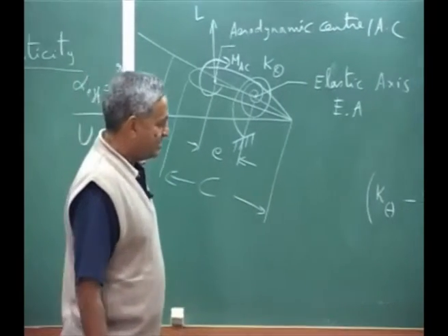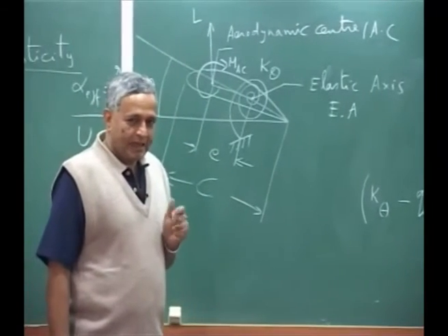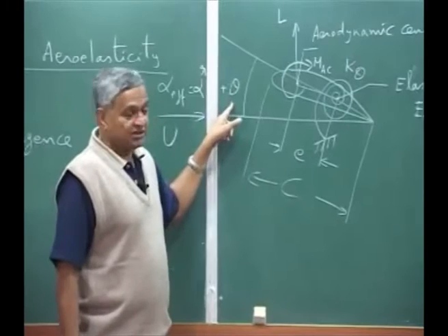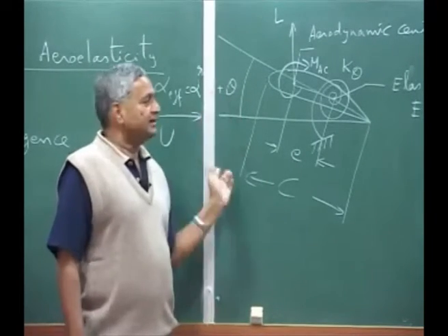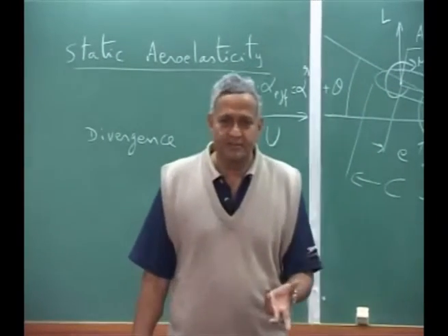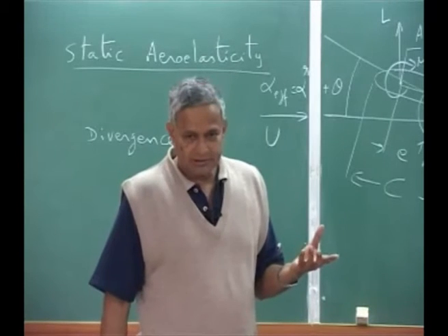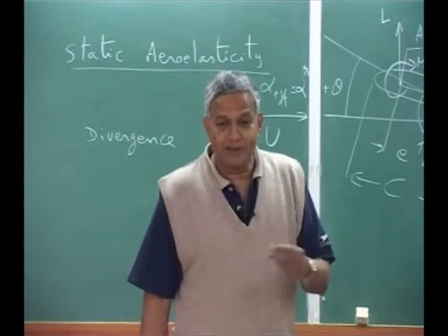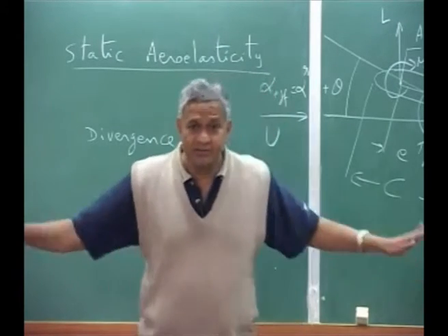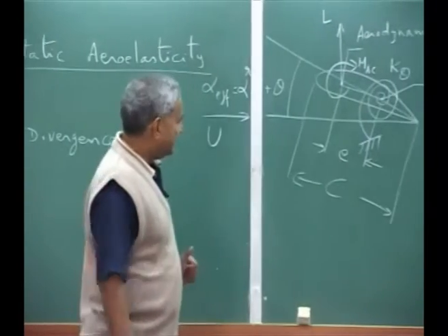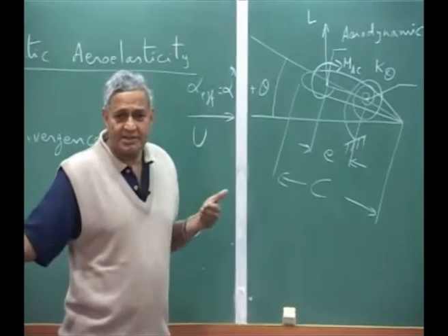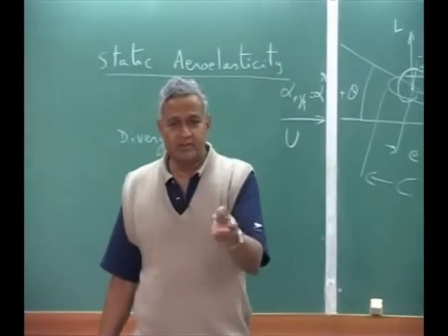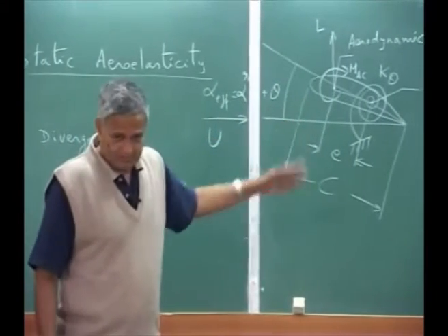What we have done is essentially we assume first, because there is an elastic deformation, that the angle of attack has changed. Therefore, my lift force is changing. On the other hand, usually what people will do is, if I don't consider the elastic deformation in the estimation of my air loads, that is like a rigid airfoil. If I don't consider, then what will happen? My alpha, this is like in a wind tunnel test. Wind tunnel test, what do you do? You put it at different angles of attack of a rigid model and measure the lift, the moment, etc. Drag. Here we are neglecting the drag force, basically.